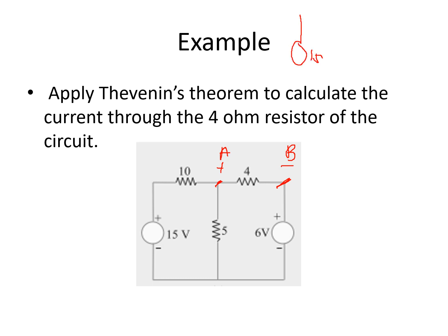So you have 15 volts, plus and minus. You have 10 ohms here, you have 5 ohms here, and this is open. We have 6 volts here, plus and minus, and this is open. So let us call this A and B. This is our VTH, plus, minus. Okay, so how are we going to solve for the voltage across this one?